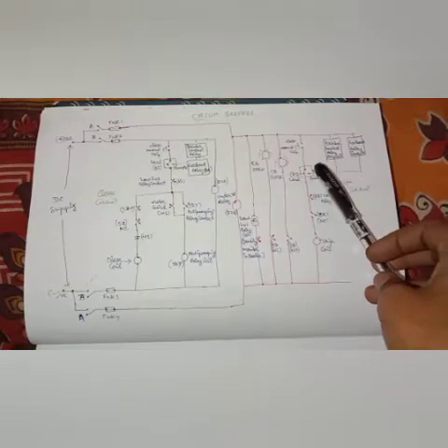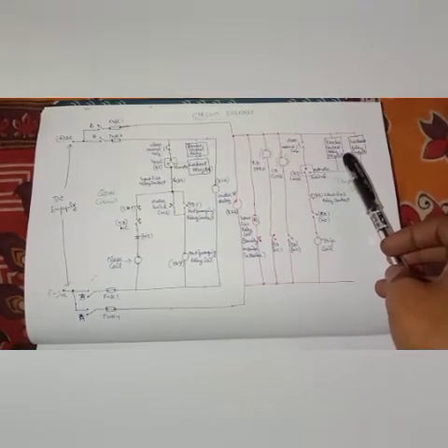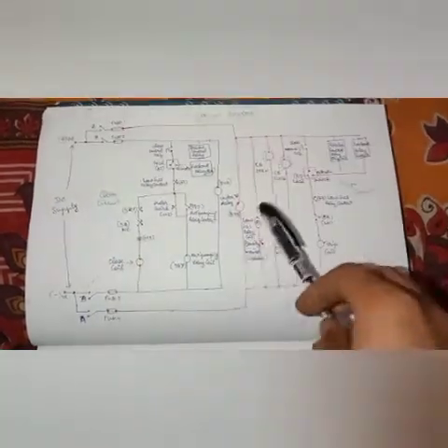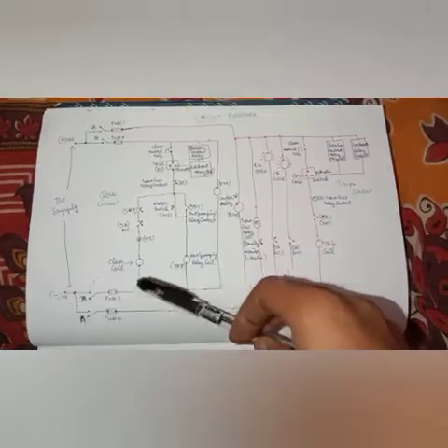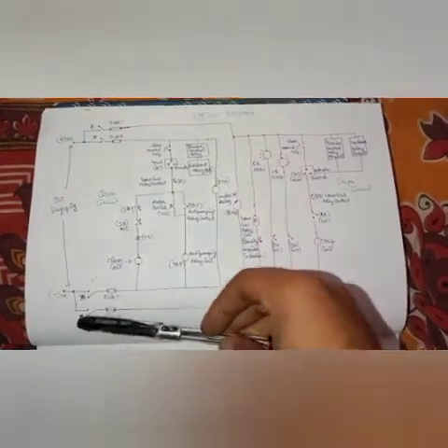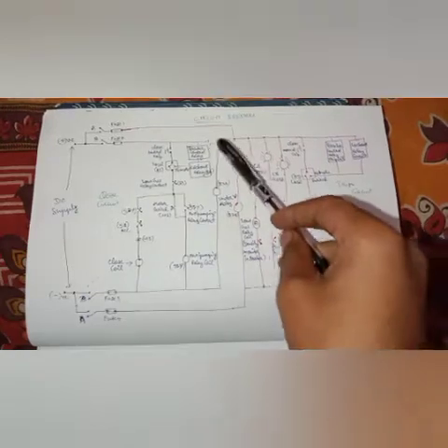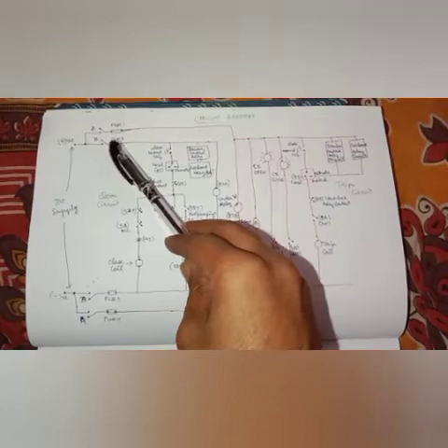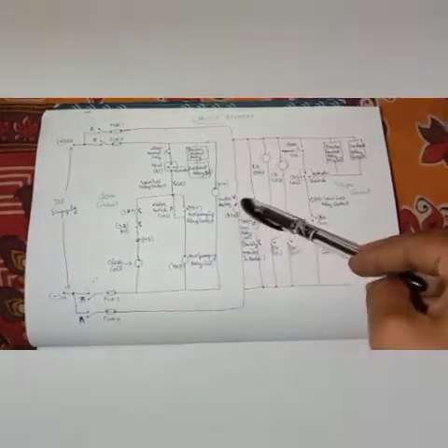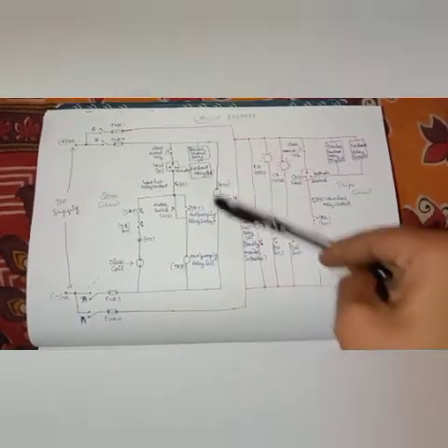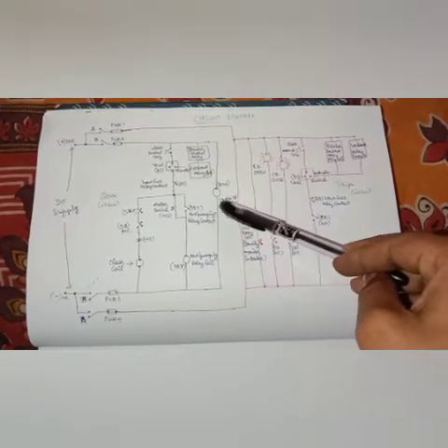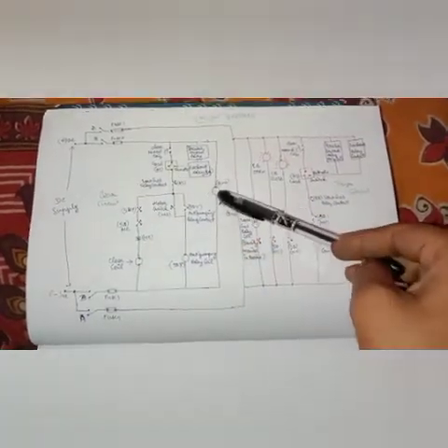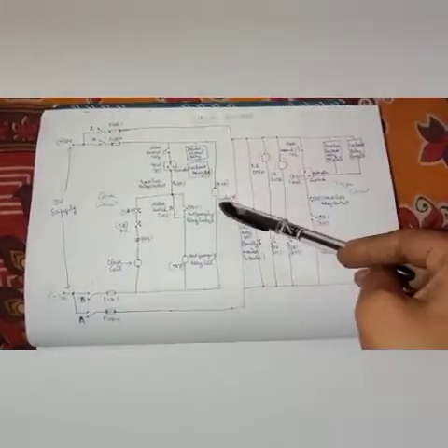So for that we are connecting these breaker control relay trippings and lockout relays in parallel condition for the tripping circuits. So these are all the things in your basics of your circuit breaker closing circuits. Then if the fuse is blasted, or if the MCB tripped, then the 27 under voltage relay is connected with that. So with this we can take the MCB status, which means the healthy status, and the DC supply healthy status can be taken by the